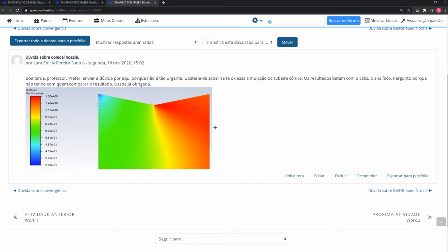The flow is horizontal. You gave a horizontal initial inclination of the flow, and here it is not compatible with the wall because it's inclined. So the flow must rapidly change its direction, and it means that it will decelerate with respect to all other points.